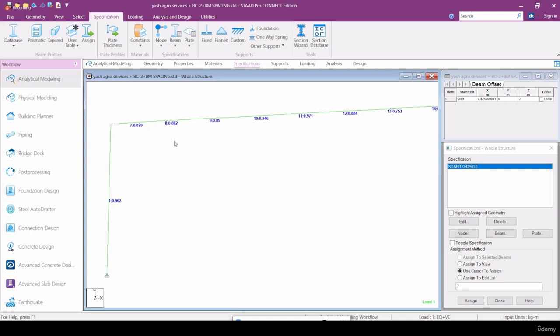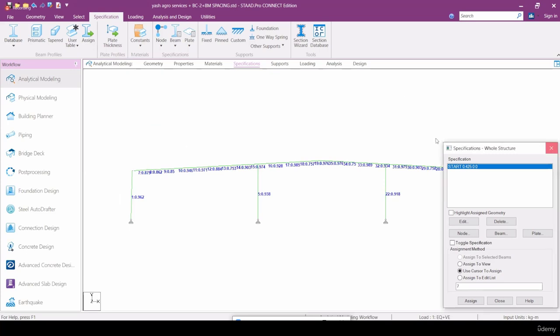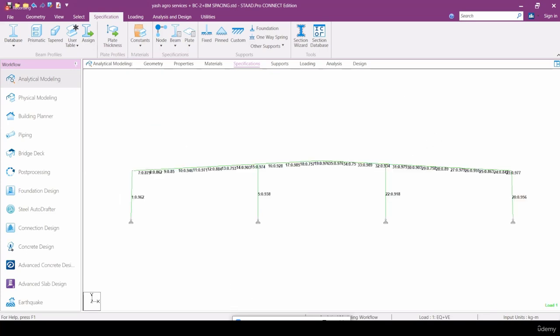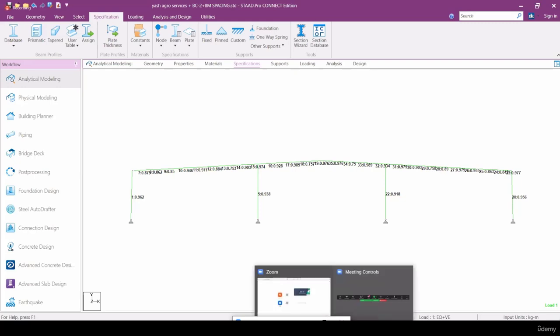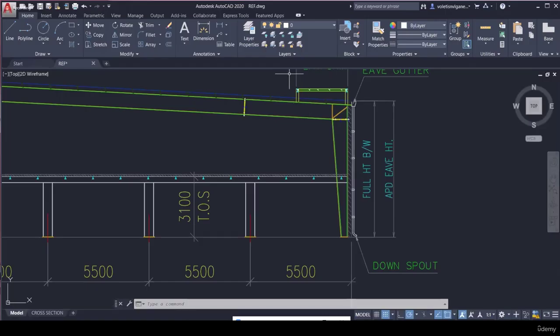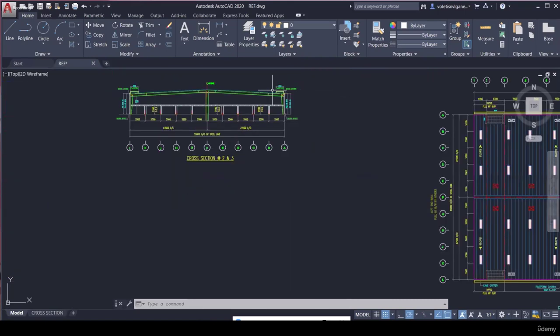While doing mezzanines, we have to use this concept, because mezzanine loads will be much higher, right? So we have to use this concept in order to create more economy. Yes, exactly. Any other thing? Sir, one small question. For example, now we are considering this in STAAD, which doesn't consider horizontal knee connection or vertical knee connection.